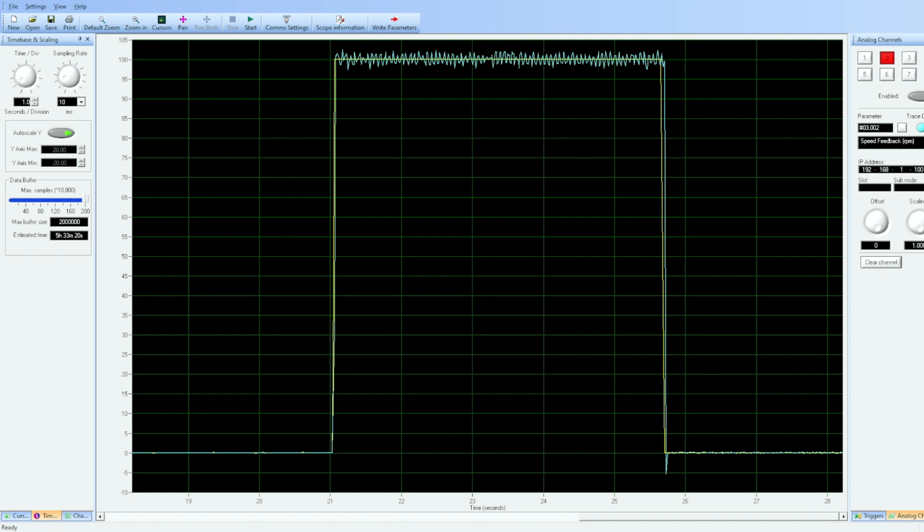Yeah, well, that's another thing to note too. If you're using the automatic gain settings, it won't let you manually adjust those terms, right? So if I have 317 set to something other than disabled, I could freely go in and adjust these things. But once it's set to high performance, it won't let me make those adjustments manually. So I'm just going to leave those alone. That's pretty good. We'll just leave it at that. When we start positioning, we'll see what happens there, but in my mind, that's fine.